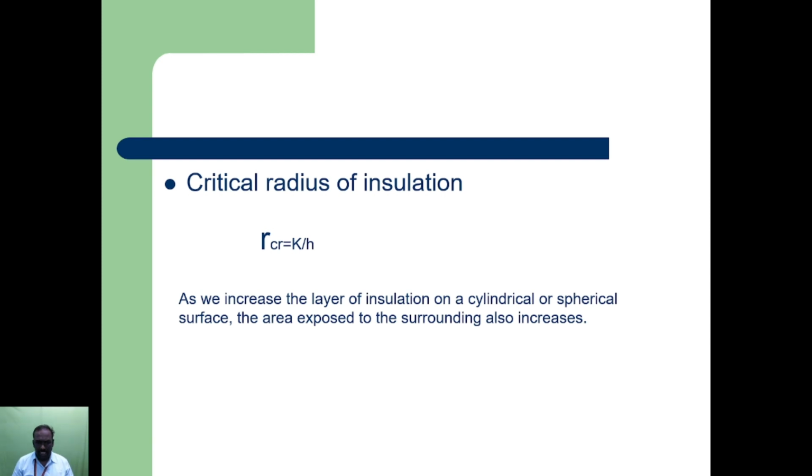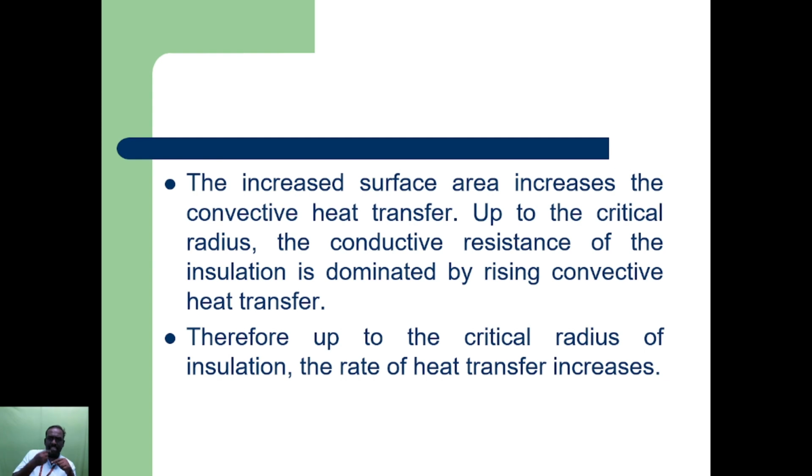As we increase the layer of insulation on a cylindrical or spherical surface, the area exposed to the surrounding also increases. The increased surface area increases the convective heat transfer up to the critical radius.